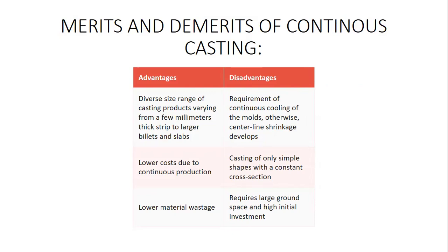Next one, requirement of continuous cooling of the mold. The mold has to be kept continuously cooled throughout the process. Otherwise, a material shrinkage problem will develop during the solidification process.